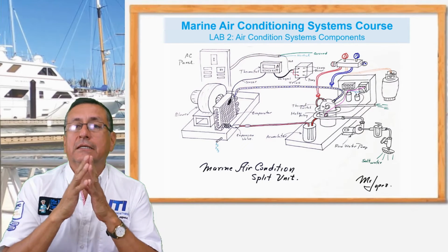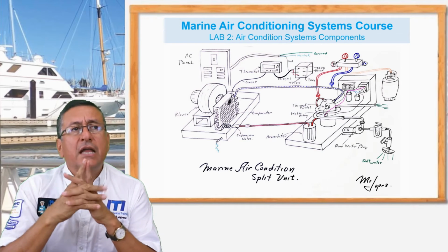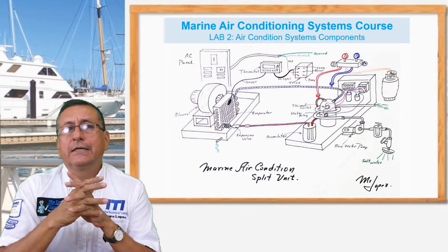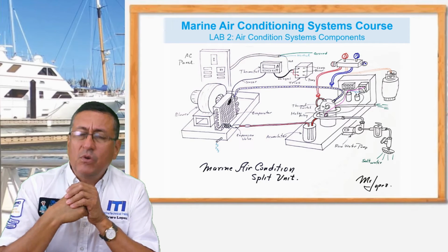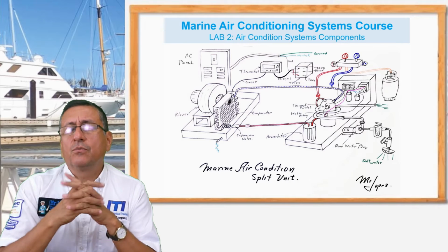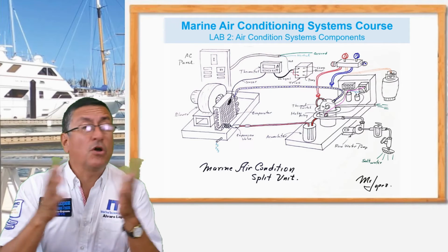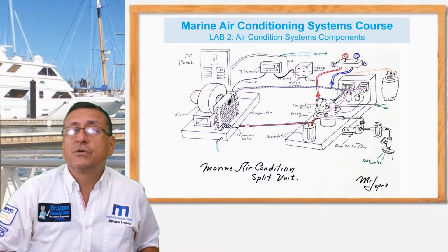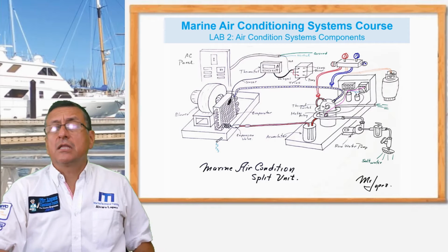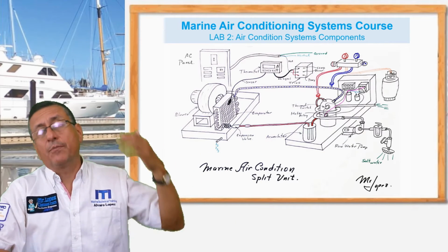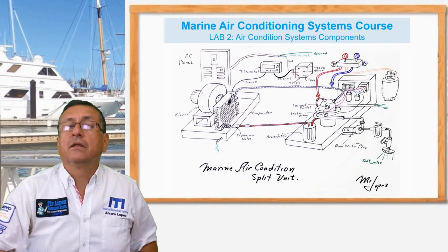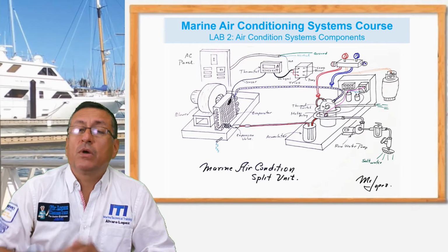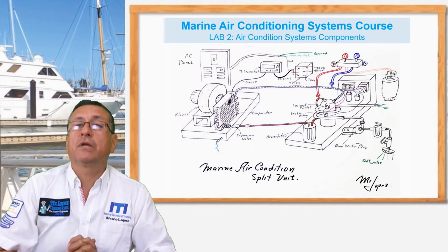That's the procedure. In what scenario do you need to verify if the compressor is damaged, or the blower? It depends on the question. What is the most common question in relation to problems with the air conditioning system? The most common question is: I start the air conditioning, I select the temperature on the thermostat, I hear that a compressor starts outside, the evaporator starts inside, the blower, but the air is warm. What is the first step in that particular case?